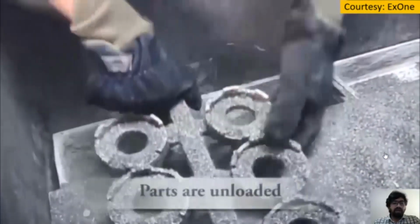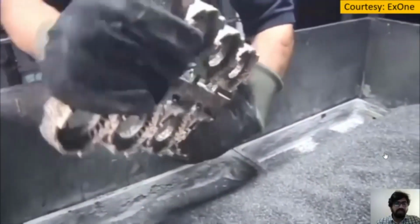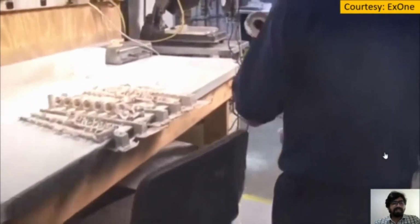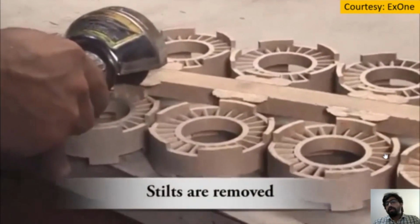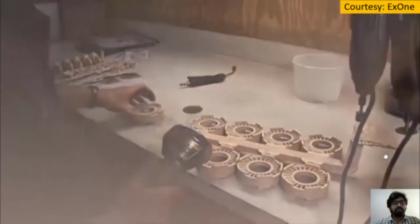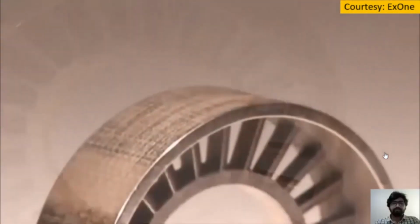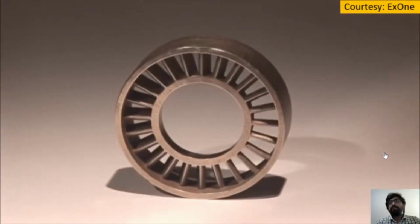As this copper has taken the space of the binder and eliminated the binder, the parts are now completely of metal and will have better strength than earlier. Then these parts are slit from the channel in such a way that we can obtain each and every part appropriately. We can really create very complicated parts by this technology, because binder based powder bed additive manufacturing can realize very large, very difficult to fabricate overhanging structures without any difficulty.